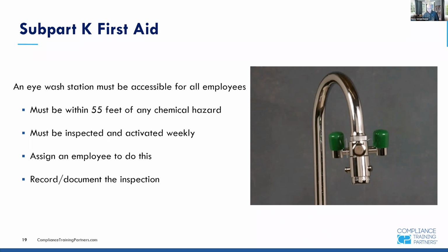Now I'm curious, since we're talking about eyewashes here, how many of you, in fact, do test your eyewash? How many inspect it weekly? How many don't inspect it? How many just don't have one, period? You know, a lot of people don't realize that you need to do it every week. I understand that. But when you think about it, bacteria grows in there, biofilms form, it won't work. Makes sense, it's once a week.